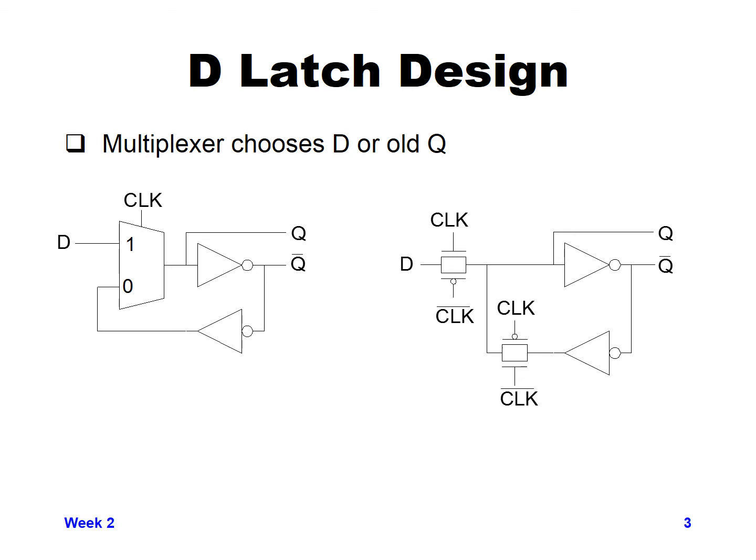If clock is high, the pass gate in the upper left that has the D input going to it has the NMOS on because clock is high, and the PMOS device is on because clock bar is low, so the D value will transfer straight through and go to Q. It will also feed through the inverter to Q bar and feed back to the other pass gate, but since that pass gate has the flipped version of clock and clock bar, it is off, so it is not fighting or trying to drive the output Q at all.